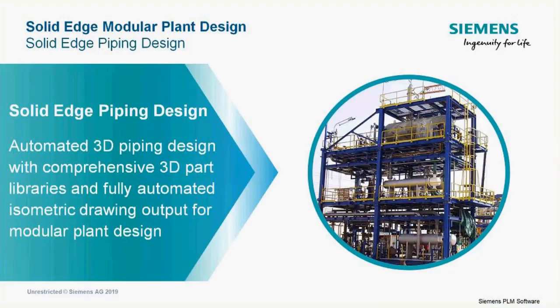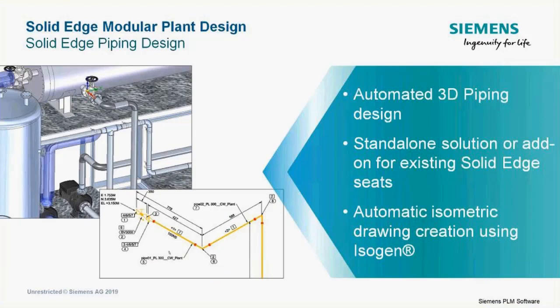All right. So then the next brings us over into the Solid Edge piping design side of things, the 3D, to where we can see how things look in real life. And some of the things about this is we're able to automate this piping design, either completely standalone, not related to a schematic, or it can be connected to that P&ID and reread that information in.